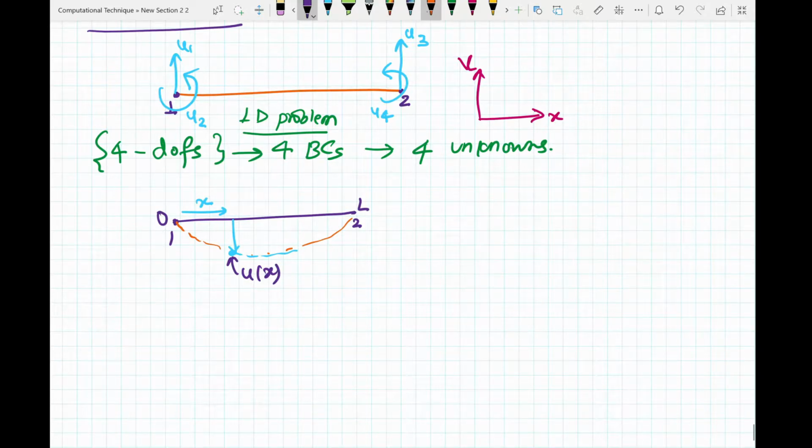Now what to do is, if the exact solution of this one be something like this, we're not sure, and we are approximating its solution by a certain curve, which is the green one. We assume this green to be our shape function or our assumed or approximate deflected shape, which will be given by a certain equation.